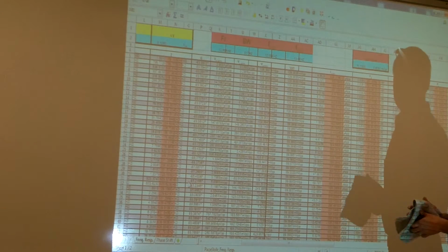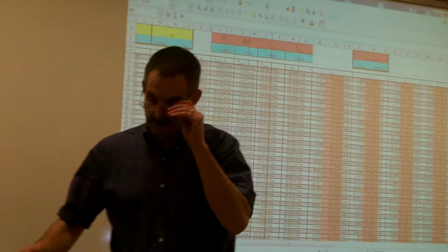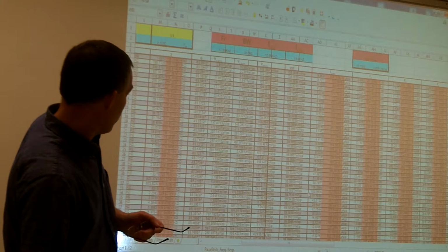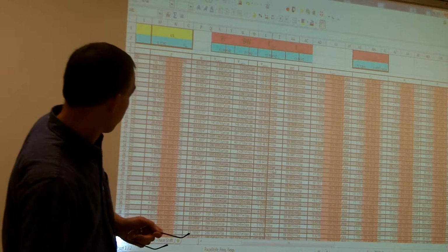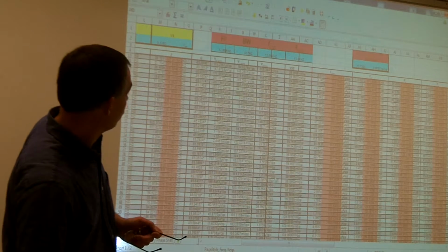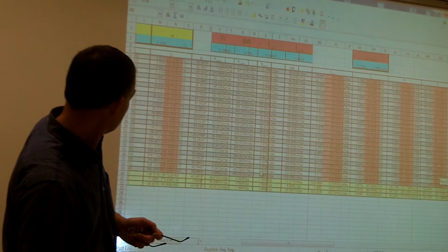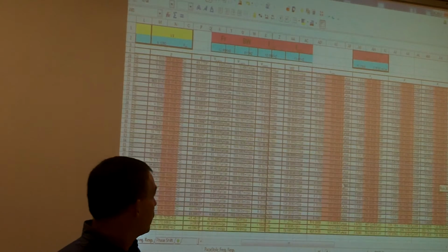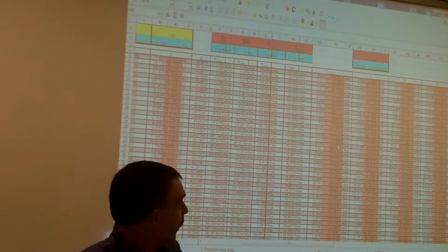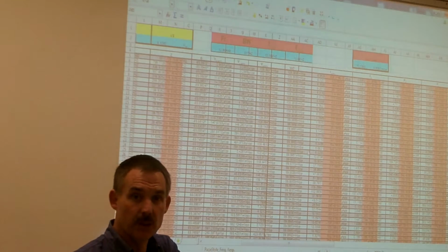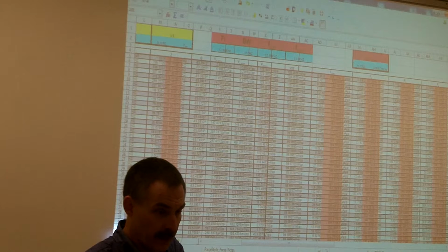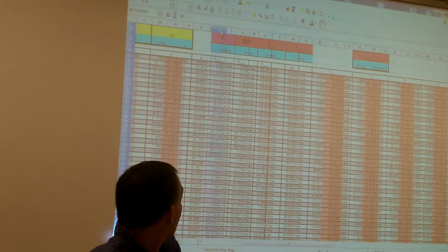My half power would be at 0.707 of my voltage source. But since we have such a large amount of resistance in our windings, our maximum voltage coming out of our resistor is going to be, what did we calculate for our output? 61.05 millivolts. That would be our maximum voltage coming out, so it's not going to be at 70.7% of our voltage source because of the resistance of the winding of our inductor. We'd have to accommodate for that when we go into our amplifier stage.